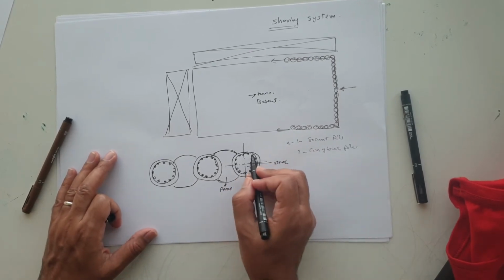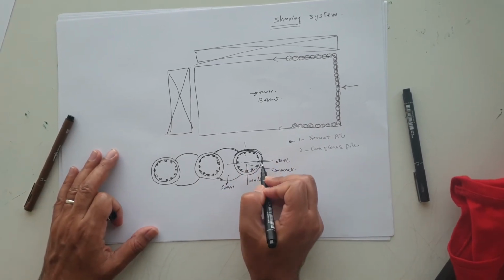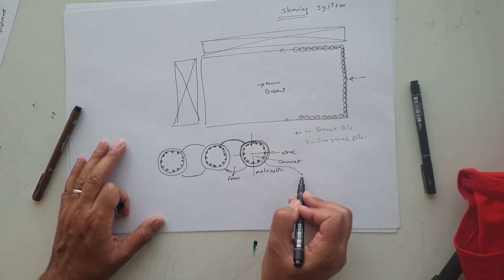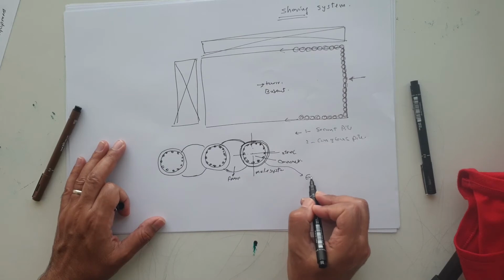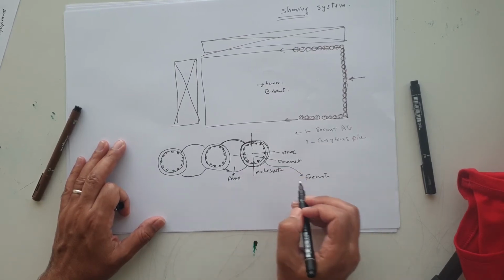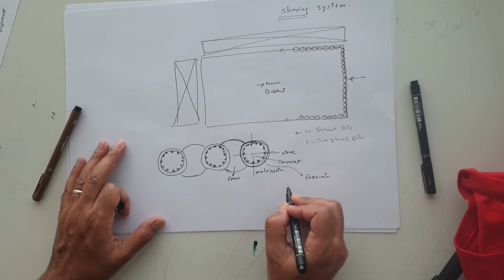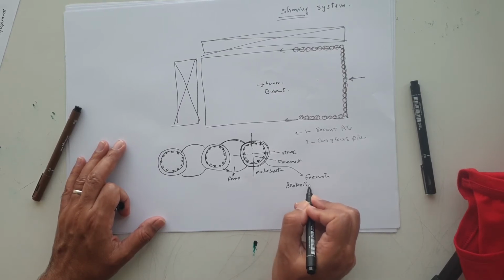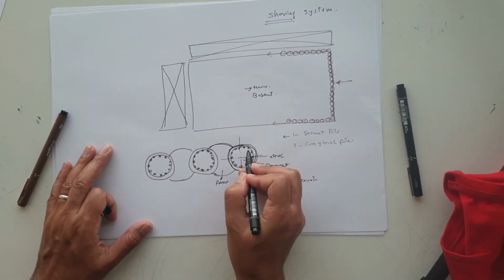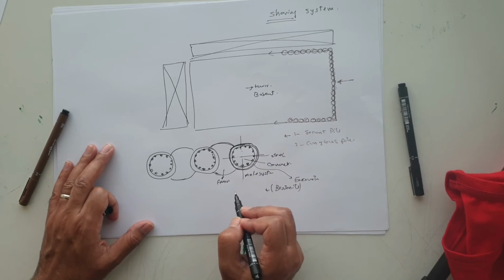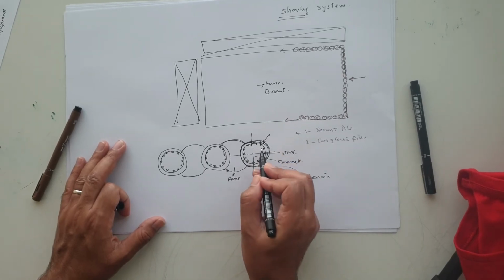In the pile system, there are a lot of issues we have to consider. First of all, we use a machine to make the excavation, and then we use a material named bentonite. We put the bentonite to keep the excavation area clear, and then we fix the steel.